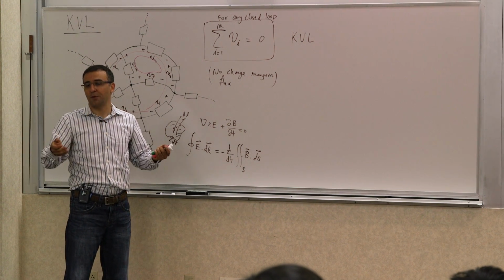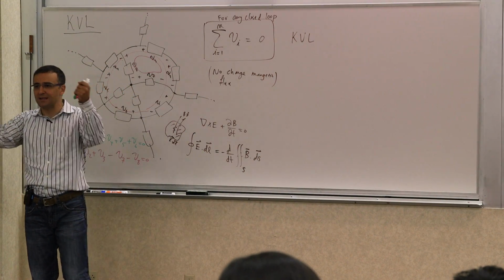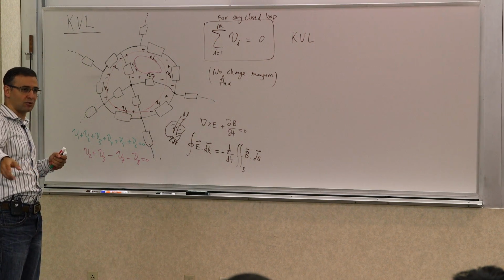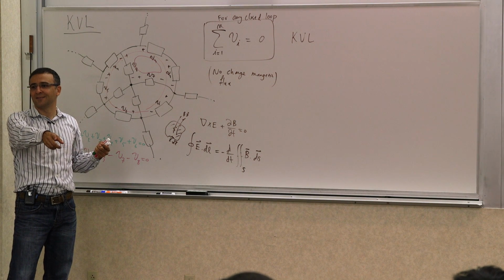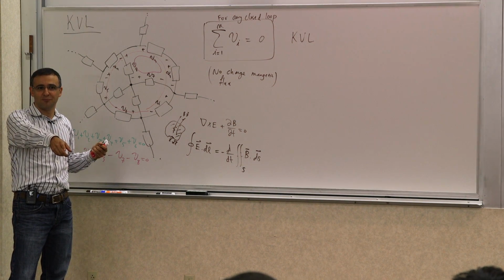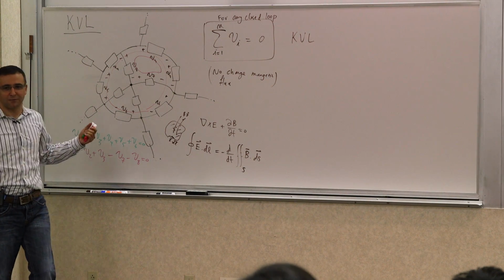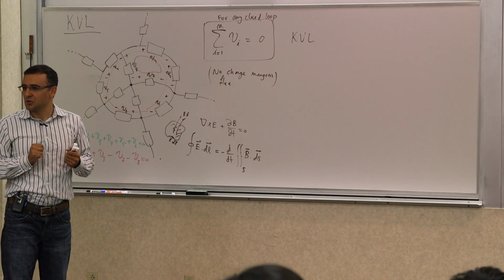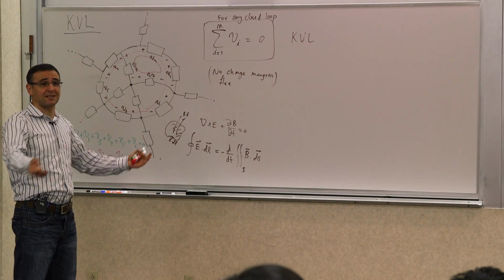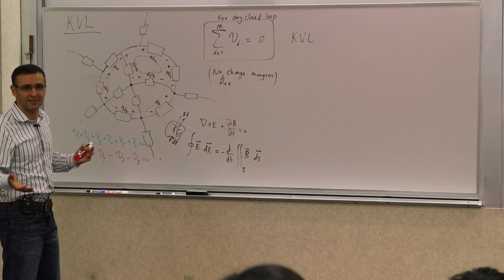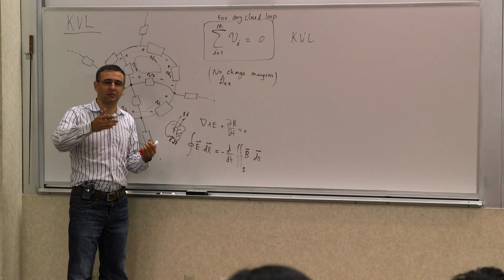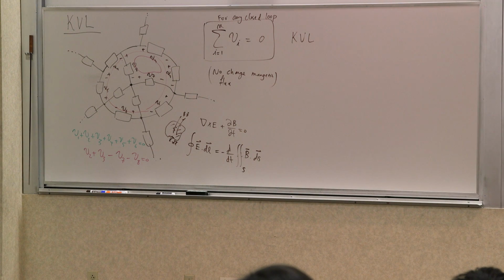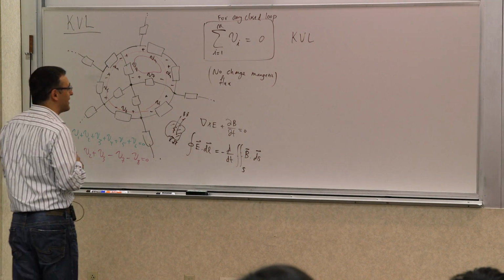All the power transmission network is based on transformers and magnetic coupling, because you do not distribute, I'm sure everyone here knows, the 110 or 120 volts. And there's a good reason for it, which we can discuss in a few minutes when we talk about the power of a resistor. So you distribute hundreds and thousands of volts, and then you bring it down to 480 and 240 and 120 and things of that sort that you use locally. Those are perfect examples of that. There are many, many examples.